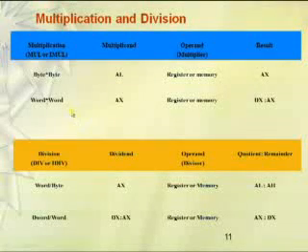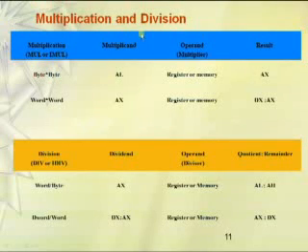Let us see. If you are performing a multiplication between 2 bytes, then the multiplicand should be AL, and we have to specify either a register or else a memory location. This register or memory will be multiplied with AL, and the result will be stored inside AX. And if you are doing multiplication between 2 words, that is AX and a 16-bit register or 16-bit memory location, then the result will be stored inside DX and AX. That is why DX is called the extended accumulator.